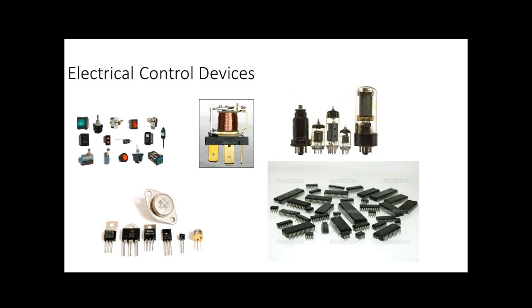But these are not what we consider to be solid state. These are electromechanical devices. Now your car is an electromechanical device, and what's the problem with electromechanical devices? Well, now you've got two things that can fail, right? They can fail electrically or they can fail mechanically. So that's the problem we have with relays. Even though they're widely used today in high current applications, a lot of the stuff has moved over to devices that have no moving parts.